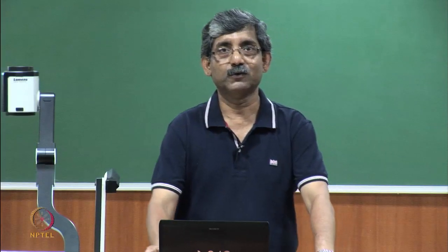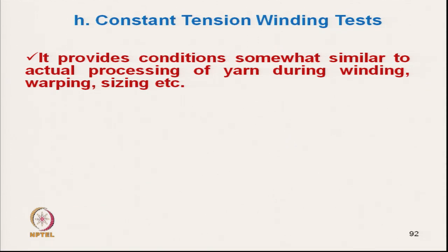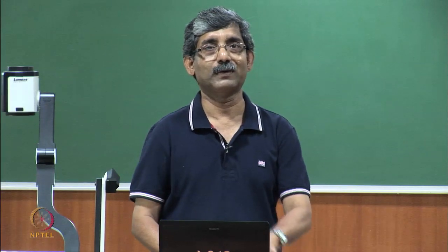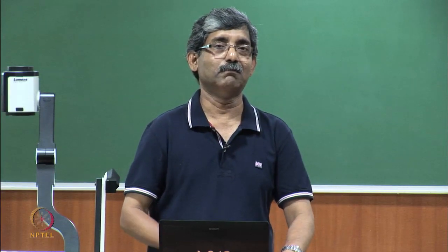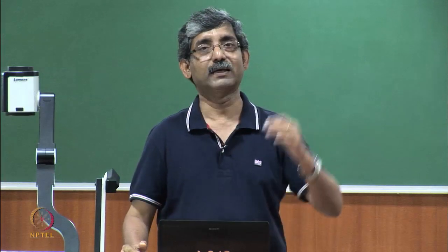Hello everyone. So, we will continue with constant tension winding test. As I have mentioned, it provides conditions somewhat similar to actual processing conditions during winding, warping, sizing. Basically, most of the breakages occur in the yarn during these processes, winding, warping and sizing. After that, obviously in weaving also, during picking.